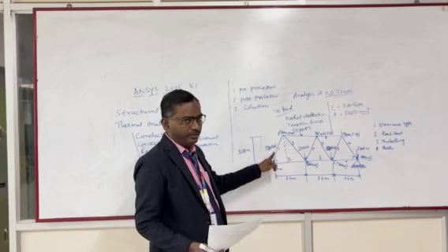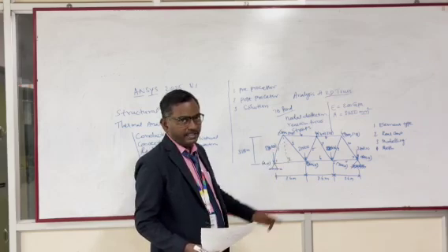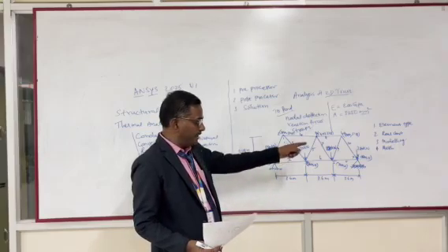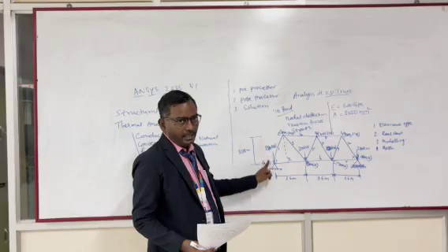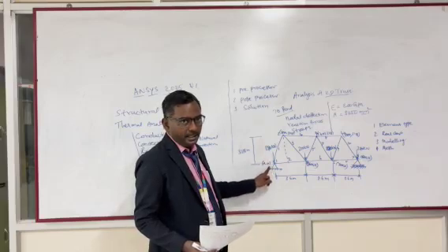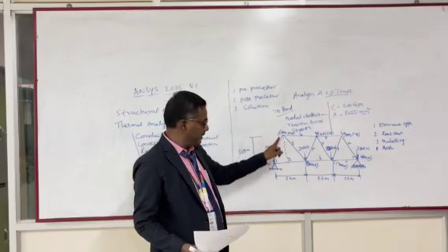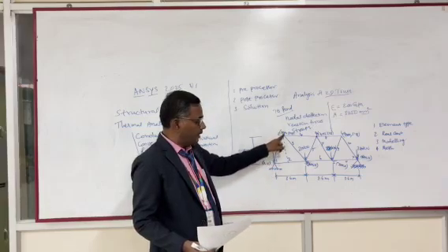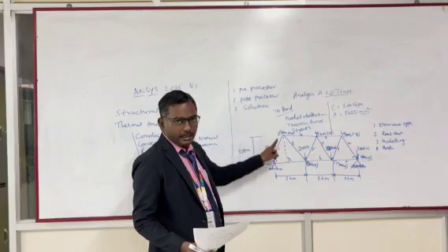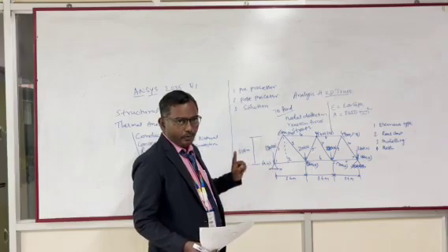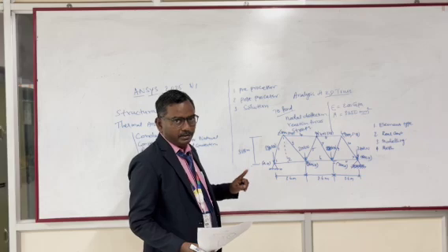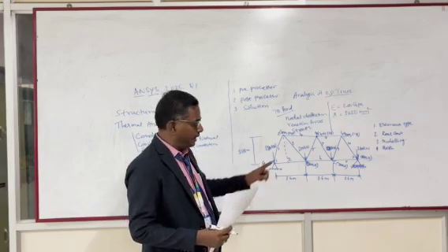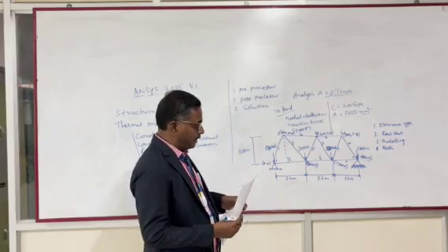That's not giving us the size of the mesh. So you can give mesh size as each element, each layer, give it one element. Okay, can select the one element. So then you can work.